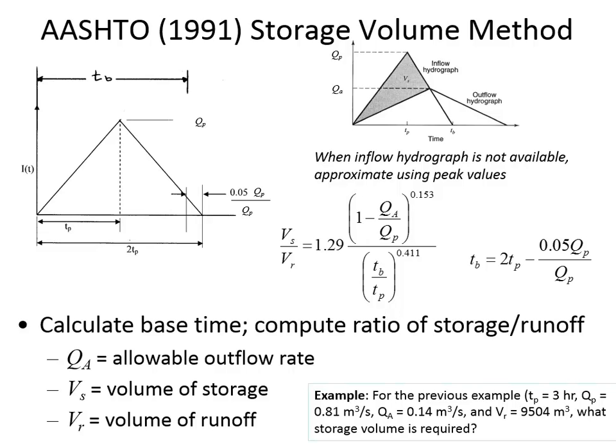If you calculate that, you get 12,260.16 times 0.9714 divided by 1.325. That's all equal to 8,988 cubic meters. So that's the volume of storage required if you take into account the difference between in and out.